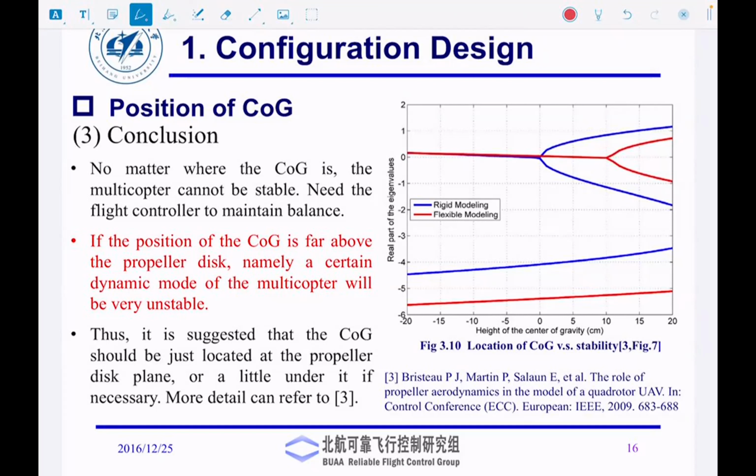Now, it's not very intuitive, but please understand, when the seat assignment is done, they take this into account. You have a cargo plane, and initially you don't know how much cargo is going to get loaded, or what the weight distribution of the passengers will be. But when they assign seats, they take into account the age and possible weight distribution and assign the seats accordingly. Also, there is something called the stability margin, which means for the aircraft, usually the CG is in the front so that the aircraft flies in a stable fashion.